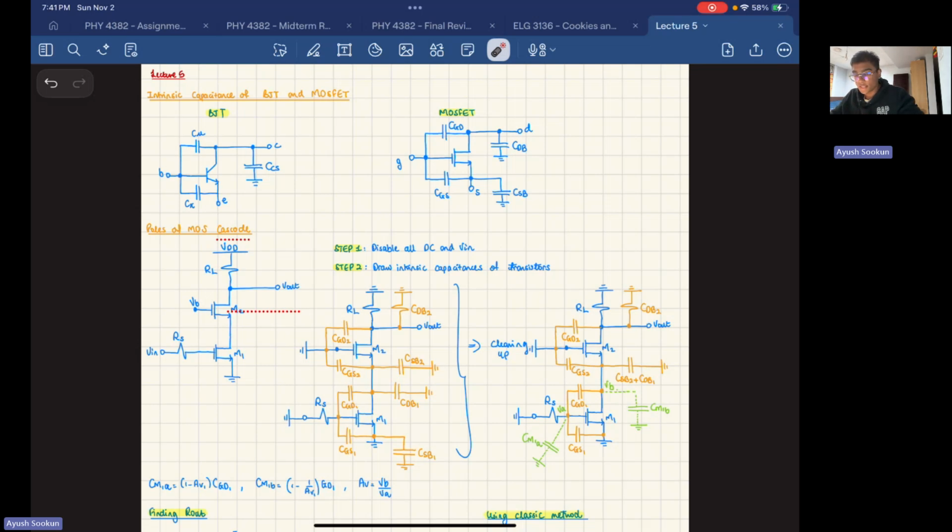So to model these electric fields, and remember, electric field is related to the voltage, what is an energy storage element that is a voltage device? Well, it's a capacitor. So you're going to use that capacitor to model and talk about this capacitance and its effects inside of that BJT.